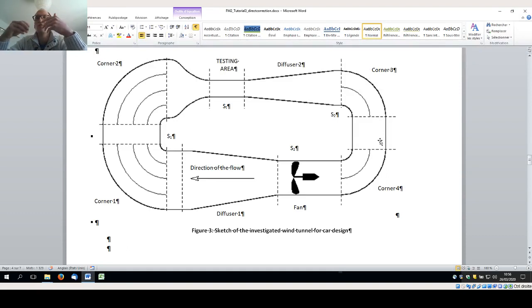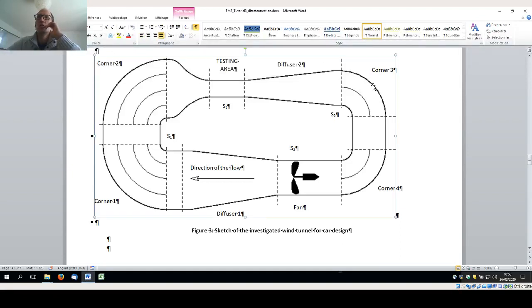So what is more important in this particular configuration are the singular head losses. This is why we are neglecting the other one, because we have a lot of singularities. We have the four corners, and the presence of the grid. You were also asking about the grid.